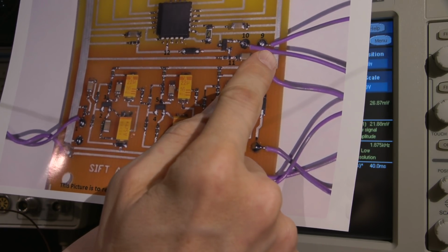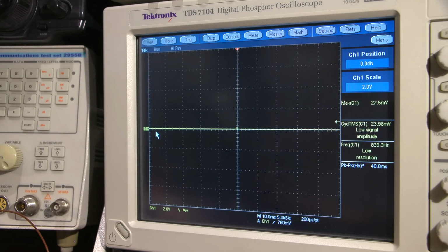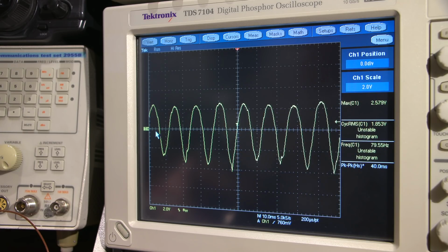Now here's something that might catch you. This is something to keep in mind. Okay, so I'm going to attach the positive of this back up again. Now what I'm going to do here is turn the gain potentiometer right down for this test. Because we're at this point, the gain potentiometer here will cause not much of a movement. It'll just make what I'm going to display a little bit clearer here. So I'm going to attach my oscilloscope probe back up to test point number 8 again.